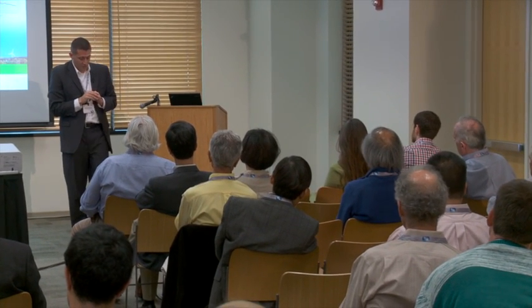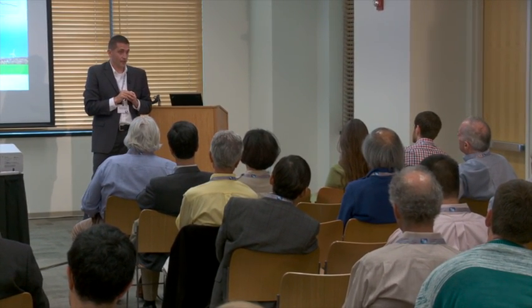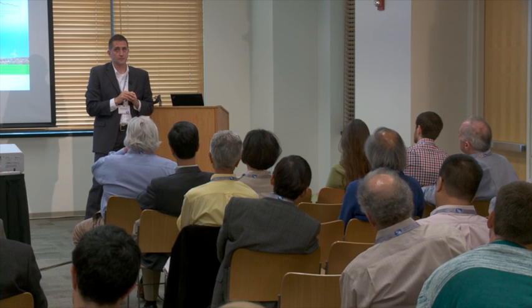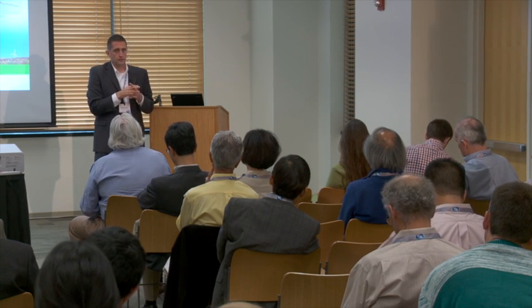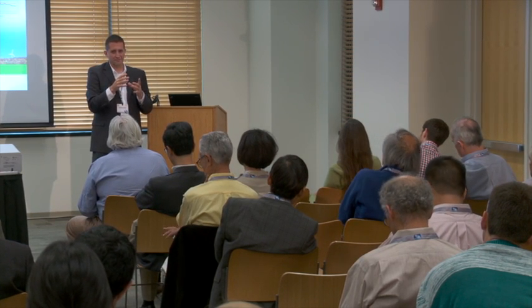So they do create quite a bit of wake effects, which are to some extent not well understood. There's a lot of research going on in terms of wake propagation. Typically, the wind turbines are sited 5 rotor diameters apart from each other, and the idea is that a lot of the turbulence caused by the wakes has smoothed itself out to an extent. So you do see some differences in terms of the turbulence on the back turbines, but not that much if you space them out far enough.